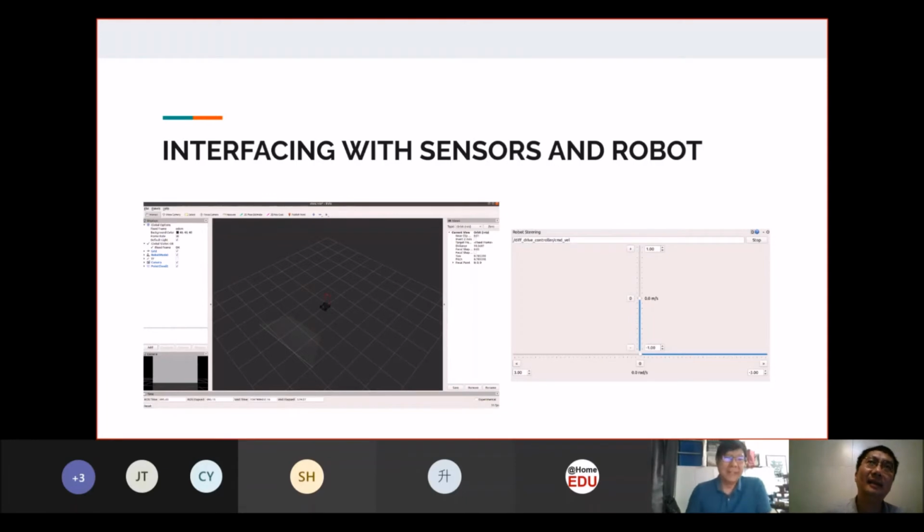But let's say we want to do collision avoidance, for example. Yes, then the shape is actually important, because a rounder shape or a sharp shape is different. From my understanding, because I don't really work a lot in Gazebo, especially when we deal with navigation, we need to know the shape, which is defined in the Gazebo format, which is a bit different from URDF because URDF is used in ROS. Maybe you can share with us a little bit. It's the SDF, right? Yes, SDF file.